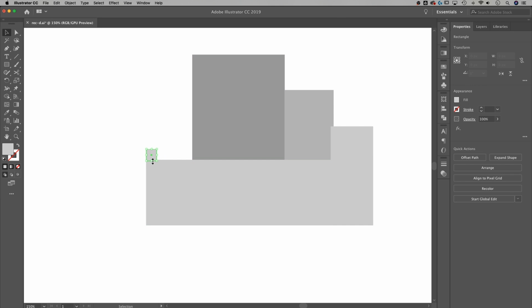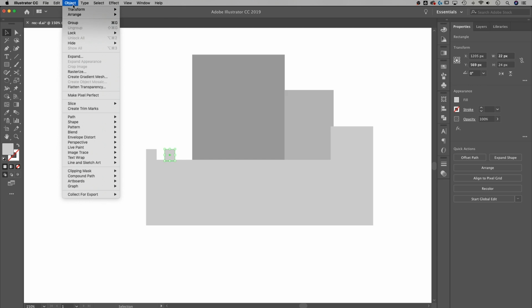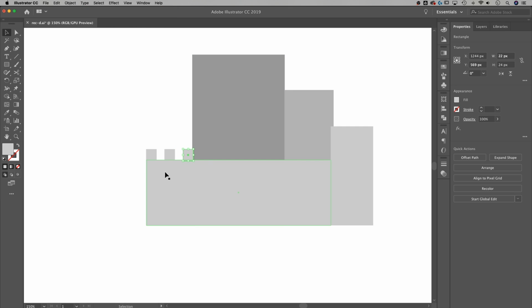The next thing we're going to do is just duplicate this over. I hold Alt or Option and Shift and give myself whatever spacing I want, just like that. Now what we're going to do is duplicate again. Going up to Object, down to Transform, actually it's called Transform Again. That's Command or Control D as a shortcut key. When I click that, it just does the last transformation again, which was the duplication we had done. So I can hit Command or Control D and duplicate that all the way across. I just keep pressing D. And I think I'll probably stop it with that piece.